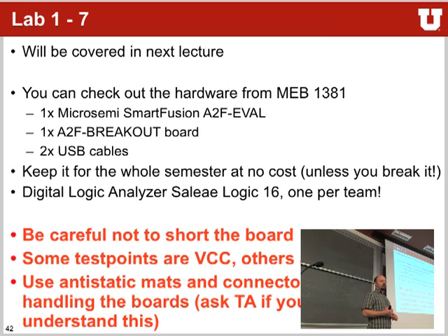Be careful not to short the board. Some of these small little pins that are coming up, some of them are power, the other ones are ground. Don't hook them up together. Don't put your leads on both of them, or bad things happen and they break. Use anti-static mats in the lab. The lab has anti-static mats, so if you are in the lab downstairs, first of all, always quickly touch the ground so you're not electrostatically charged, and then use one of these mats to work on. Also put the hardware back into the little anti-static bags that they come in. It really helps keep the hardware from getting fried and broken. I understand, stuff happens, stuff breaks, that's expected, but just try to be careful.